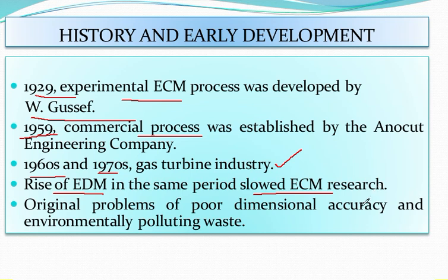The original problems in ECM were poor dimensional accuracy and a large amount of environmentally polluting waste. To avoid this, a new process rose, electrodischarge machining, and the increasing demand for EDM decreased the demand for ECM in the history of non-traditional machining.